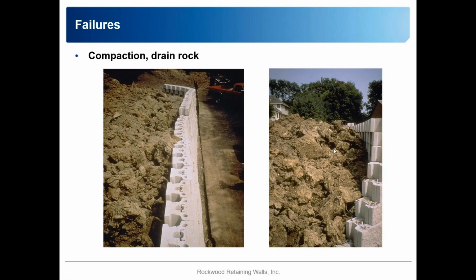And that completes the sequence of the process of leveling the units, erecting the wall face, placing compacted material, all the way up to our top of wall elevation. Now I've got just a couple slides left and want to illustrate why these best construction practices are important. So in the previous slides, we were talking about the importance of keeping your lift size down to 8 to 12 inches, using good backfill material.